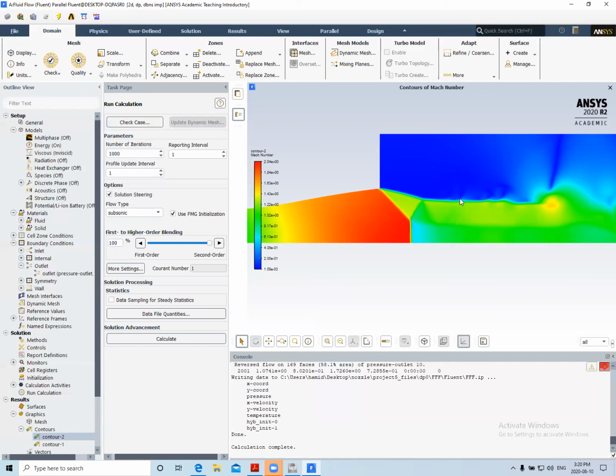But one thing is that you see some curves here, which is a result of the unsteady feature of this simulation. Actually, this simulation is not steady and two-dimensional. That's why you get some vortices in terms of curves, which means the flow is unsteady. But as we saw in the residual, it's not really low enough.